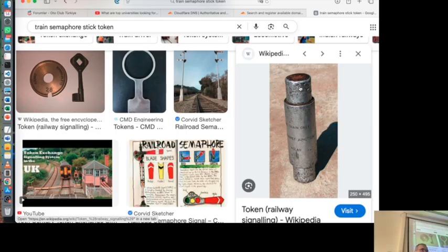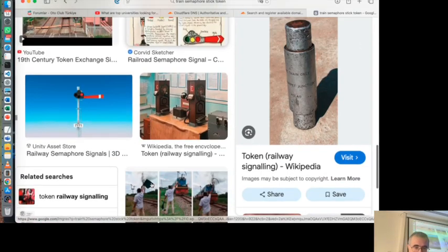Once you leave the token, the other train, because there is only one token, the other train going from Istanbul to Izmit can take that token that you gave and enter the one-line railway, because that single token eliminates two trains going in the opposite direction on the same line. Because there is only one token, and that token is either on this way or on that way. Someone will have that token.